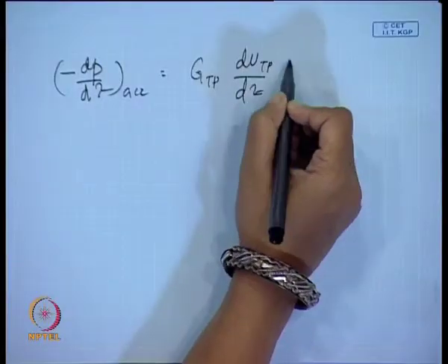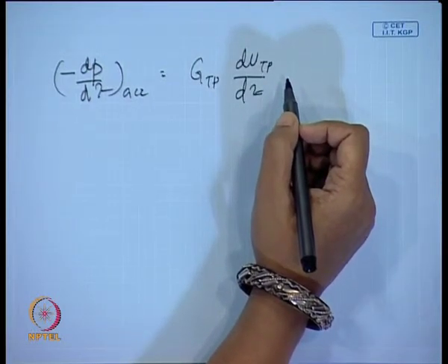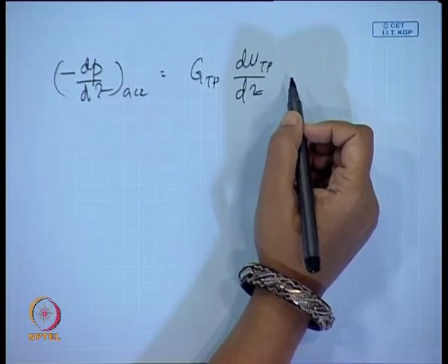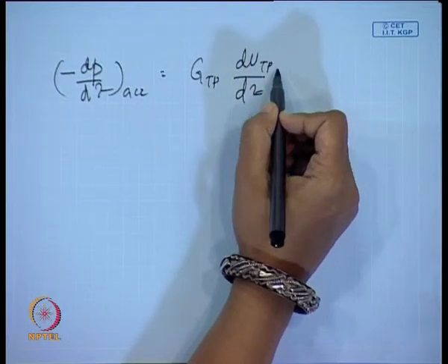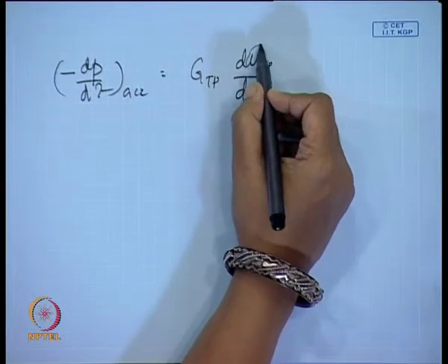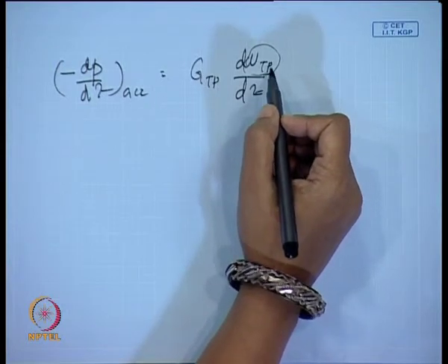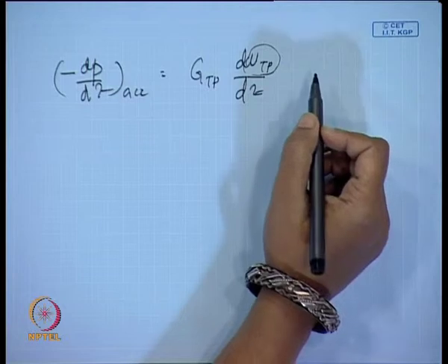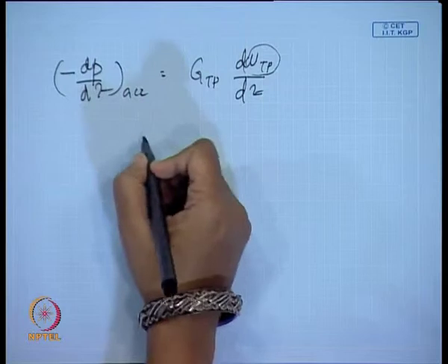Agreed? So, therefore, this acceleration pressure gradient arises just because one of the phases is compressible, or in other words considering the compressibility of the phases. And there is one more thing, if there is an area change. So, therefore, in order to evaluate dP_TP/dz, what do we have to do? We have to express it in terms of those particular quantities which will be affected with axial distance, or which will contribute to your acceleration pressure drop. So, how can we express it?